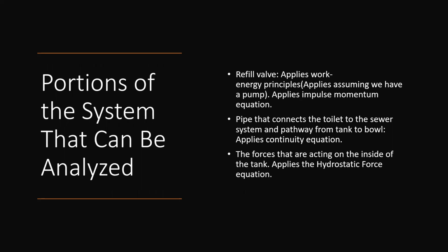So these are the portions of the toilet system that could be analyzed using fluid principles. The refill valve applies both work energy principles and the impulse momentum principle. The pipe that connects the toilet to the sewage system and the pathway from the tank to the bowl applies the continuity equation. The forces that are acting on the inside of the tank apply hydrostatic forces.